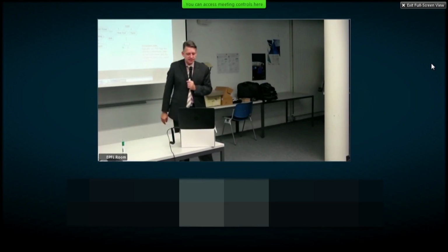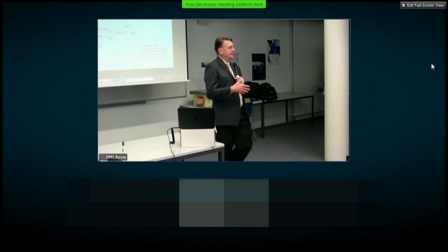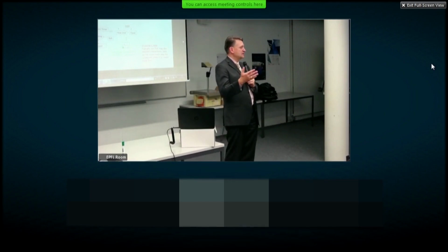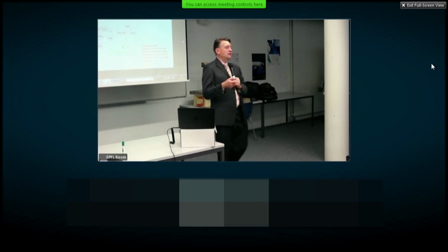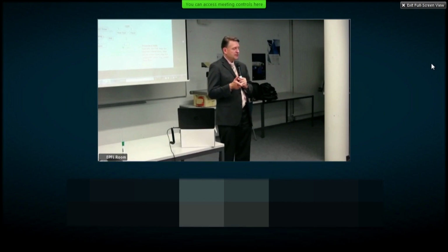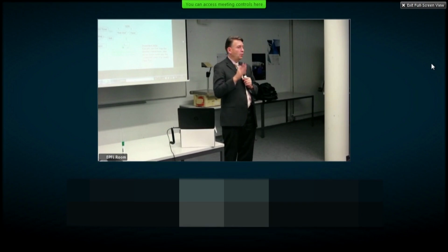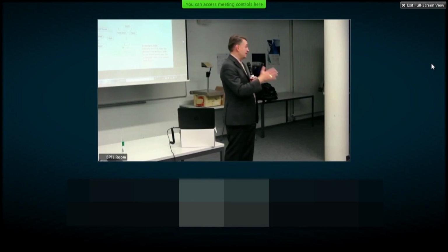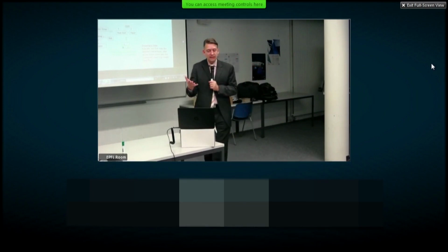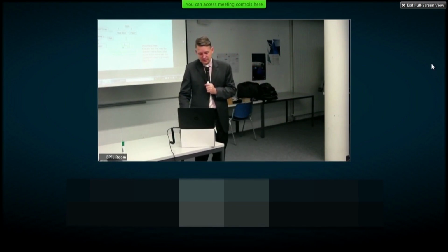One question that often comes up is, well, what if we have waste heat? There's heat losses and there's parasitic energy flows. Do we care about those? Do we represent those? And the answer is, yes, you should, especially if they affect your performance or your requirements. So the first thing you typically do as you map out your interfaces is you map the flows that you want to happen, that need to happen, right? And then on top of that, you map out the flows that happen even though you didn't design for that, but you need to account for them. So heat losses would be an example of that, waste heat flux.